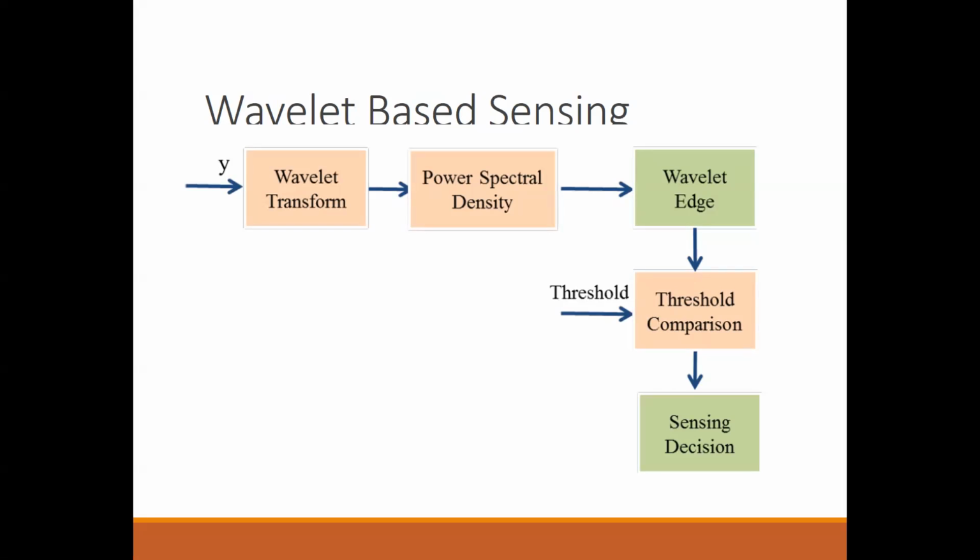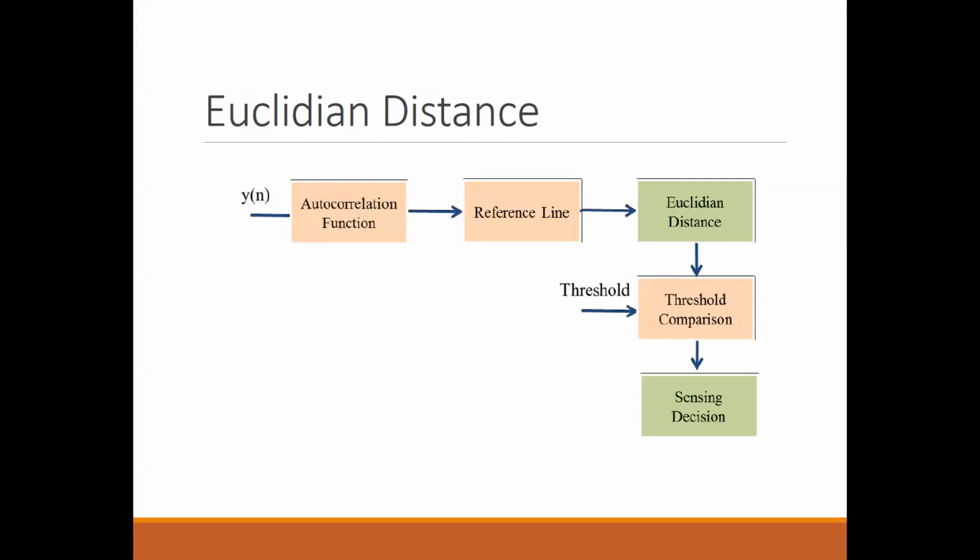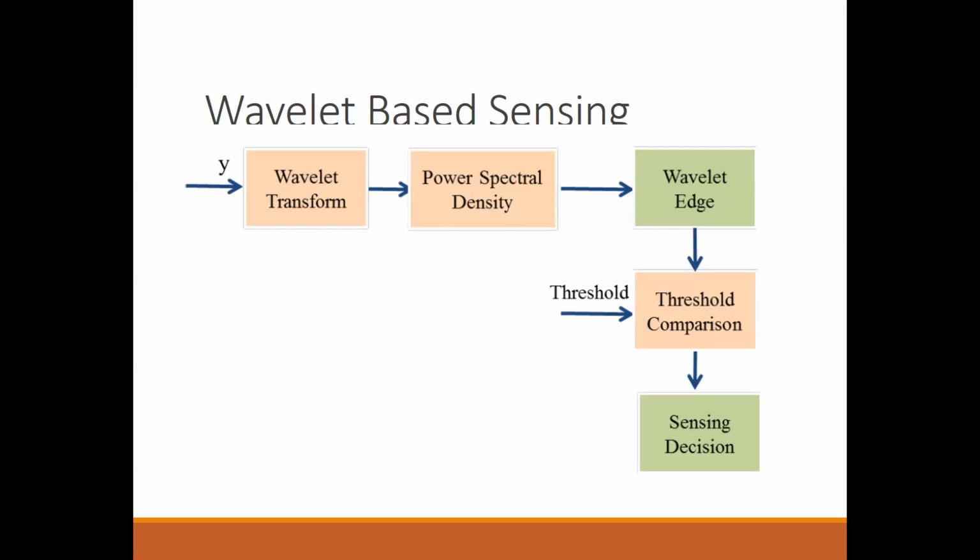So if I have to quickly summarize the difference from Fourier to wavelet: in the Fourier transform, suppose I have given you a signal, you can apply the Fourier transform and you have the spectrum, right? The spectrum tells you that there is one component at 10, another component at 12, for example. The Fourier transform can tell you what all the frequency components present in the signal are. Suppose you think of two time domain signals. One has the sum of 10 plus 12 components. In another signal, frequency component 10 comes first, 12 comes later. You think of these two different signals.